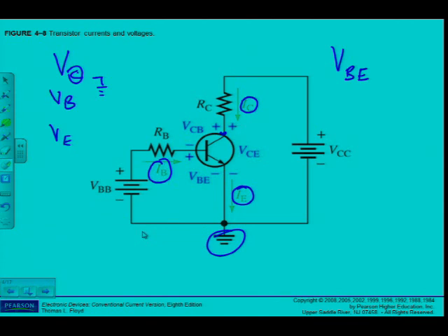And in this case, you've done series parallel circuits in electrical engineering 1. Remember I told you I'm looking here at this series circuit. So it is important that I do know my Ohm's laws and Kirchhoff's laws, because I'm going to apply it everywhere in electronics. So you must make sure that you know Ohm's laws and Kirchhoff's laws. Very important. So if I look at the circuit there as indicated at VBB, I've got a resistor RB, and I've got a junction, a base emitter junction.